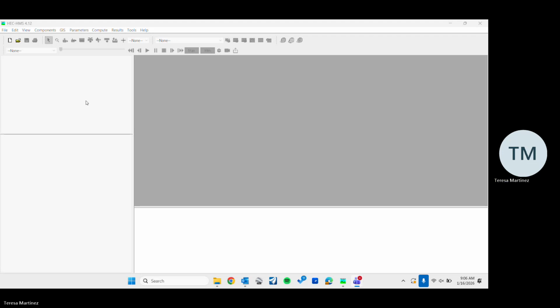You guys ready? Okay. So let's go ahead and open HEC-HMS. So I guess let me backtrack a little bit. What we're gonna do right now is use the GIS functions in HEC-HMS that's gonna automatically delineate watersheds. And I think this is a good workaround for you guys for an ORDDU instead of manually doing that, as an alternative to GIS. So hopefully this is helpful.